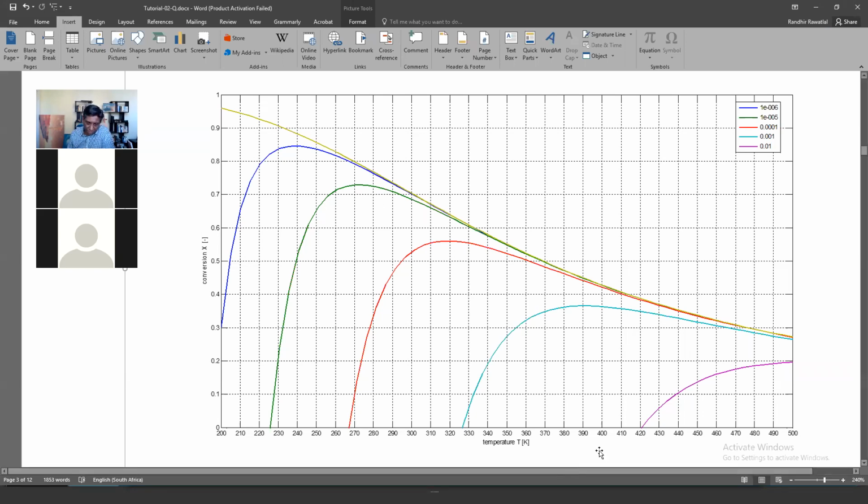And now this plane is explicitly showing us that relationship between reaction rate and conversion. So you can say generally that when conversion goes up, my concentration goes down, but this plane now shows you precisely how much it's going down by. So this isorate plane is really a useful thing for doing our design.